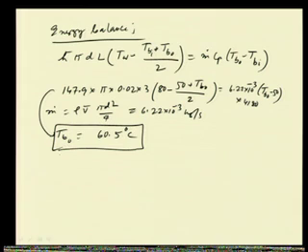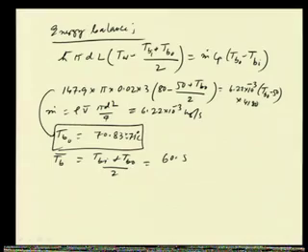So, mean bulk temperature T_b mean, or T_b average, is now (T_bI plus T_bO) by 2, and this value will be 70.83, or nearly equal to 71 degree centigrade, with T_bO being 60.5 degree centigrade.